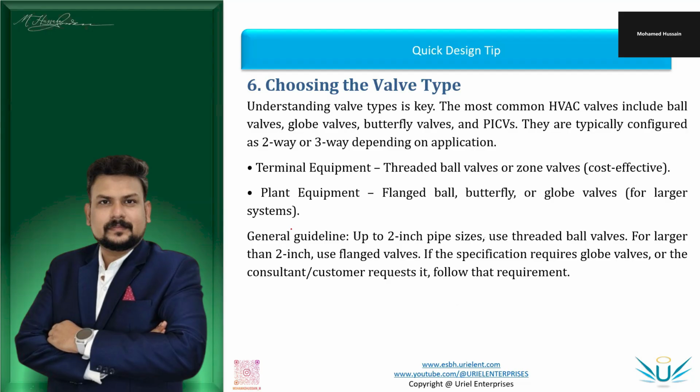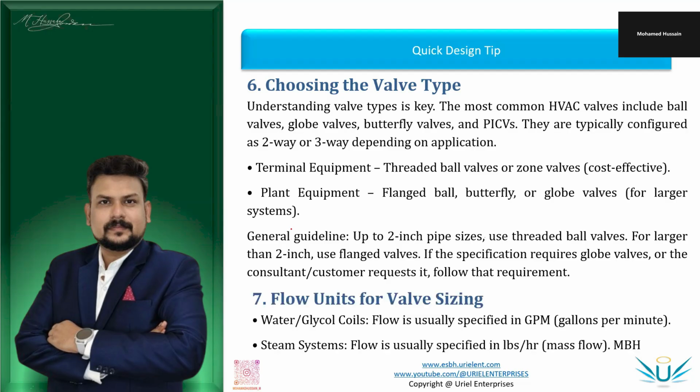Okay. Next, a very important thing is the flow units for valve sizing. If you see in the MEP drawing that your valve is for water or glycol mixed, you can see that the unit will be GPM.